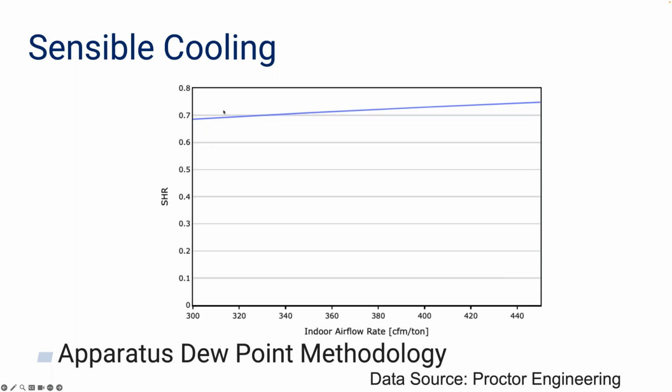All right, I'm not going to talk about sensible cooling much, but just know that there's an approach to calculate the rated sensible heating ratio based on some algorithms developed by Proctor Engineering. And then we use something called the apparatus dew point methodology to calculate for any given entering conditions how much latent heat is removed from the airstream.